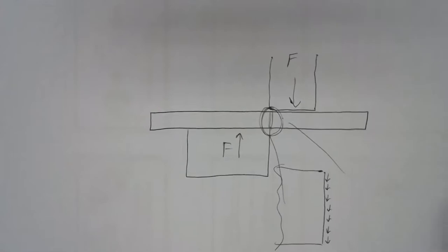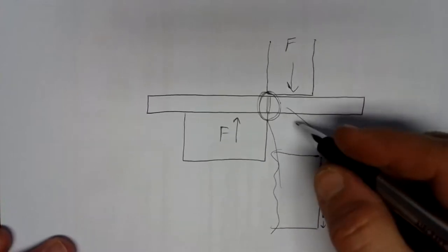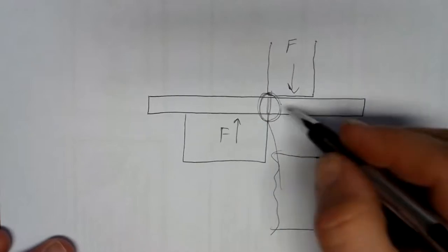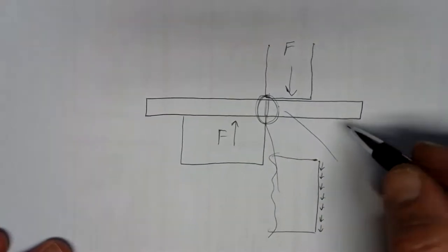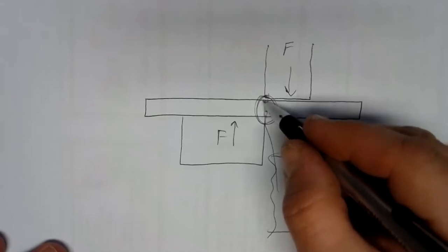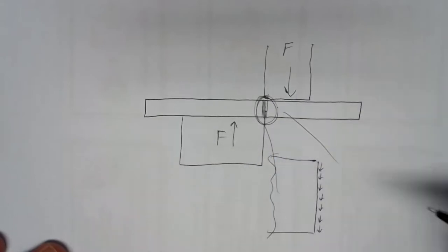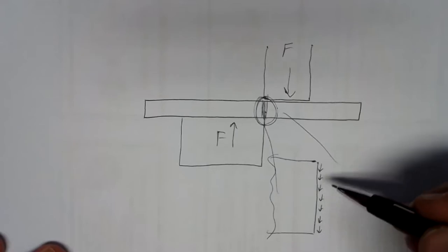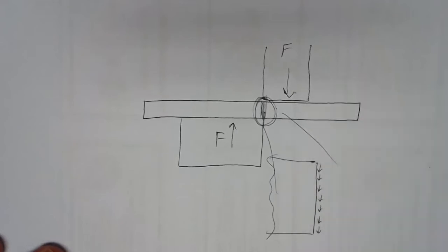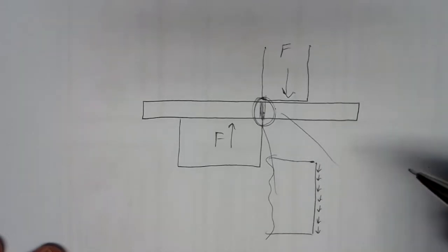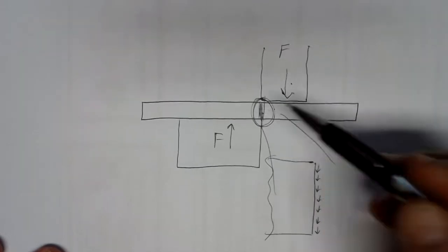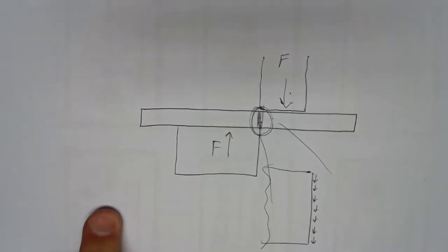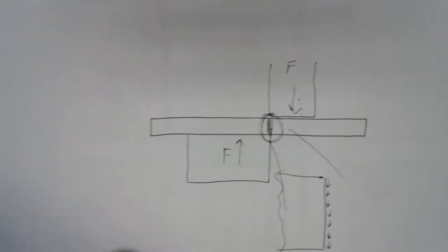If you look at our example for shearing sheet metal, think about what this is going to look like broken. When it breaks through, we're going to have some rectangle of area exposed. We'd have the end of that sheet metal, whatever thickness it is and whatever length of metal we were working with, that's going to be the part that breaks. We're going to be breaking right through the material, and that's the area to use for our shear stress. So we'd take our force divided by that area. So the area that you need to look at is typically the area that's going to break if we overload that connection.